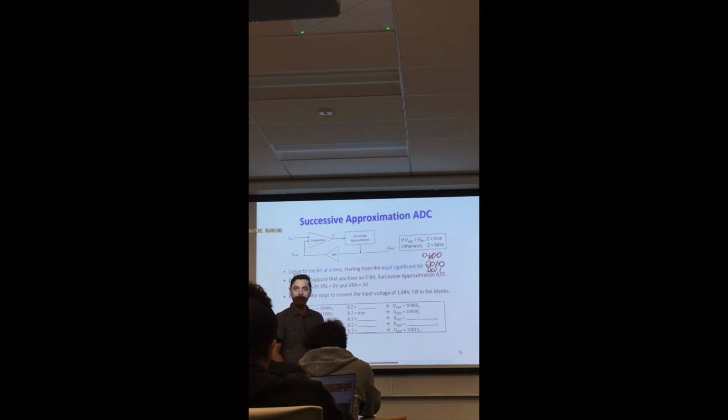Is that clear? When you set up analog to digital conversion, you actually have to think, because if you increase the precision, you increase the processing time. Is it suitable for your application or not? If your process is too fast, while you are processing it, the input has already changed, and you didn't react to it because you are designing a controller system which doesn't have a reasonable response time. So you have to reduce the precision by reducing the bit number of processing,